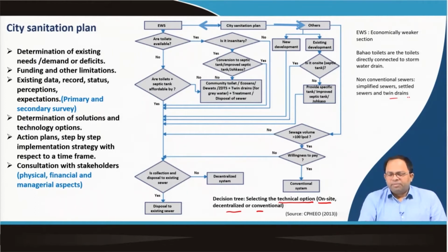So, for example, for others we can have new development or existing development. For existing development, is it on-site septic tank? If it is yes, then we go into this side the same way. If it is no, then we can provide a septic tank, or improve the septic tank, and then we again go over here. So, once the treatment part is done, then comes the collection and disposal part, which starts over here.